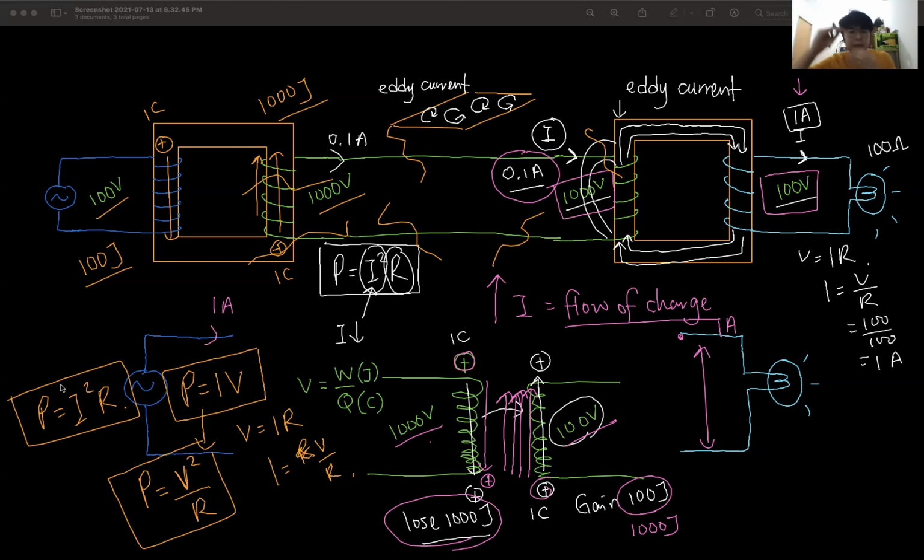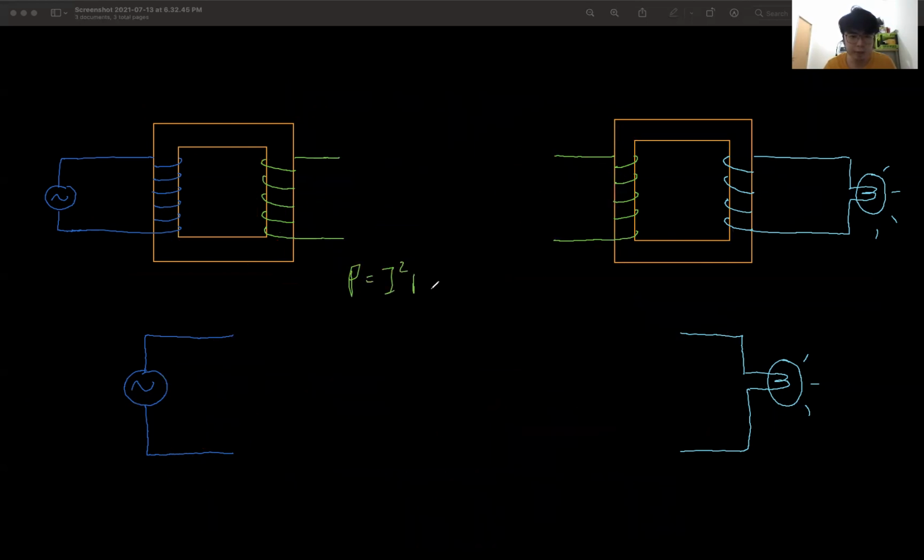这样意思说是不是那个 voltage 越小，power loss 就越小呢？本来我们讲 current 要小嘛，对不对？所以我们 step up 那个 voltage 嘛，所以我们可以 minimize 那个 power loss。可是你又有这一个 formula，这样是不是代表我的 voltage 小？OK，sorry，我的 voltage 大，我的 power loss 会大呢？OK，这个 voltage 跟你的 transmission 的 voltage 是不同的，这个要分到很清楚。OK，我先擦掉这个先。P 等于 I square R，还有 P 等于 V square R。当你要算 power loss 的时候啊，我们用哪一个 formula？我们用这个 formula。这一个 formula 你可以用，可是你要小心你的 voltage，因为这个 voltage 不代表那个 transmission